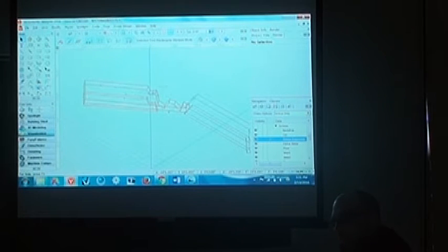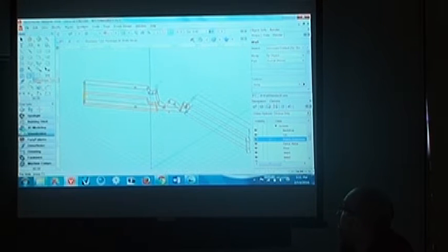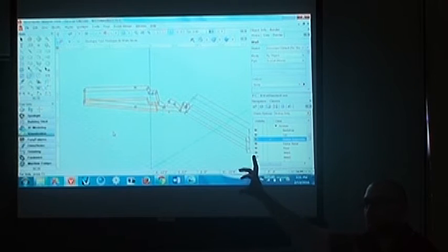If I want to create this crazy cutaway, like the T-Rex broke through the concrete or whatever, I could use my Reshape tool, which is over here, to add vertices to the wall and to move those vertices. So if I wanted to make a wall that is sloped at the top instead of just a rectangular top, I can change the vertices of the wall and now get a sloped wall.